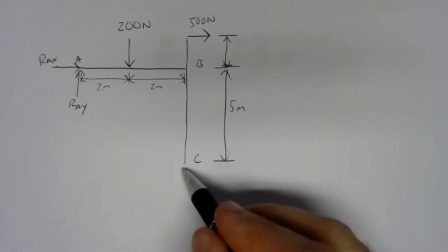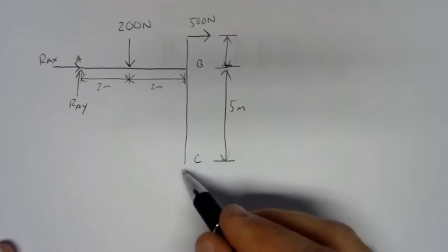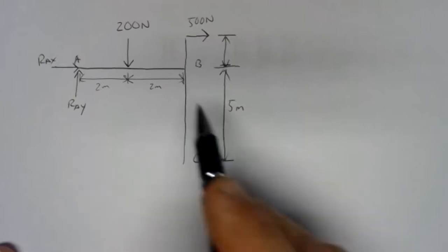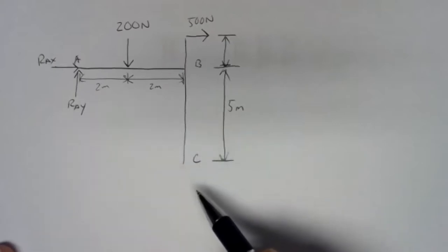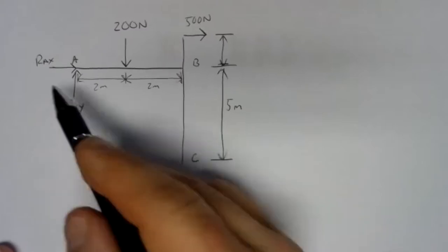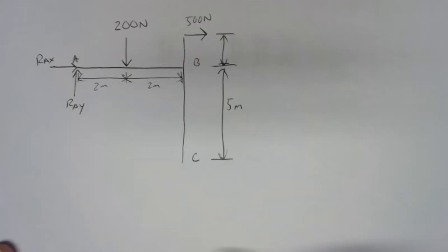At C, we also happen to have a pinned support. That's the weird part here. That's a little bit different. In all of the beam problems and even all the truss problems that we solved, we had 1 pin and 1 roller. That guaranteed that the external problem only had 3 unknowns because a roller only has 1 force. And so we'd always get numbers for our reaction forces.